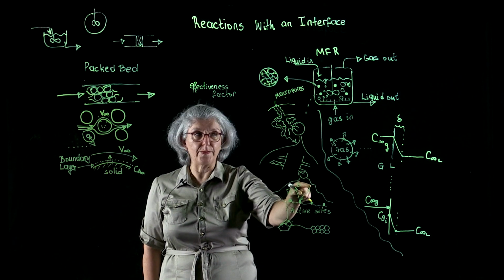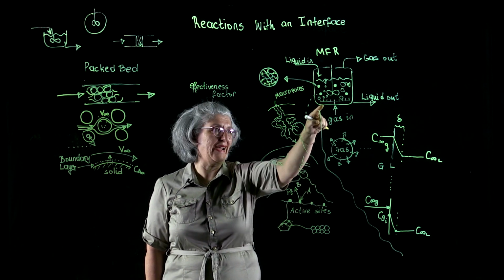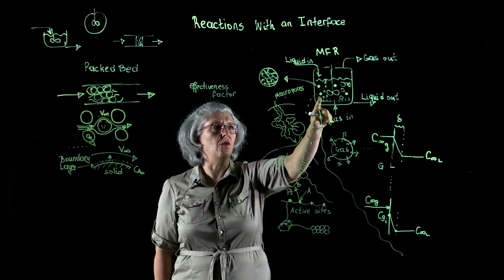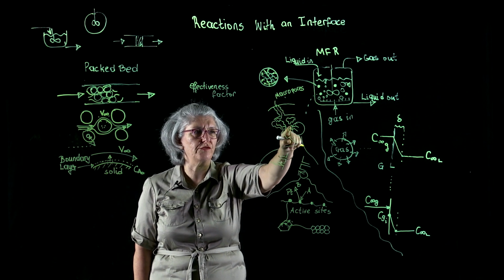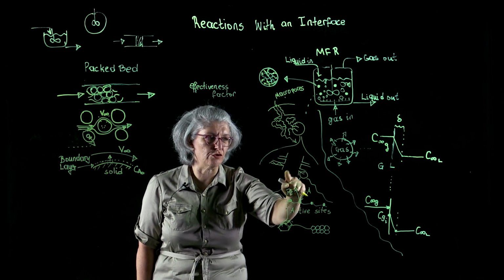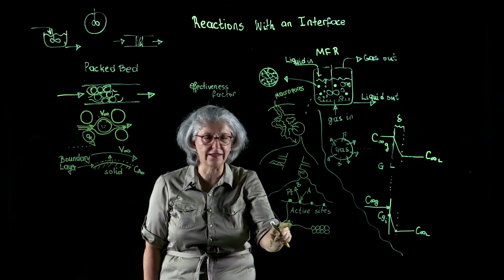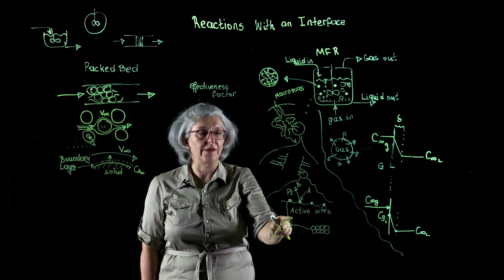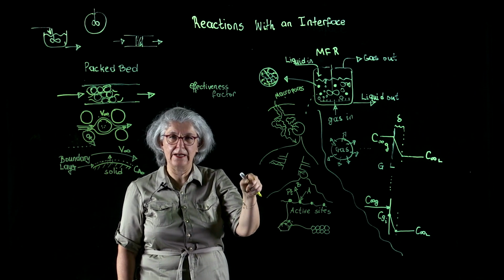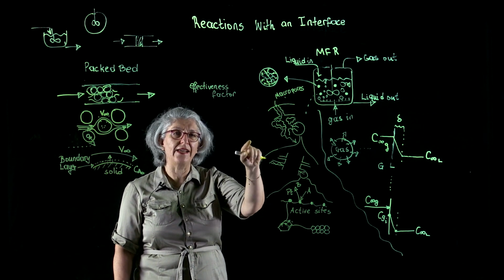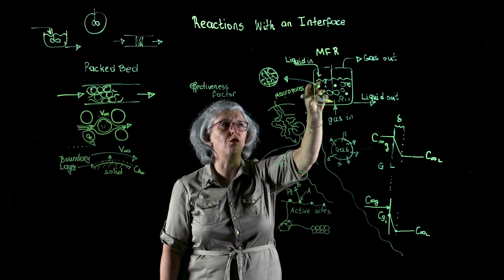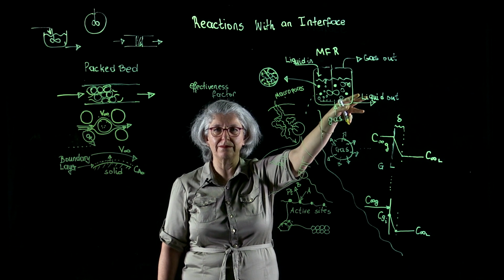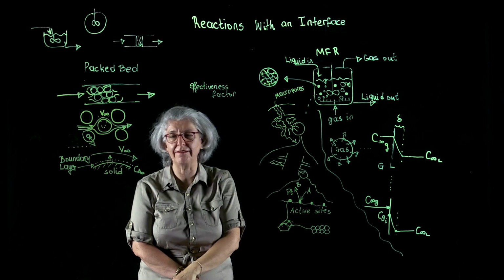Now, the tortuous path that the gas molecule A has taken, starting from the gas distribution plate, all the way through the macroscopic and microscopic pores of this catalyst, arrived at the active site, it took some time. So, if that time is not significant relative to the time that this whole fluid domain traverses through our reactor, liquid and gas, we have a very effective catalyst.